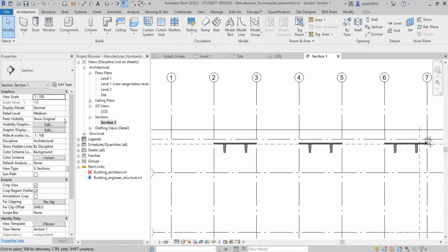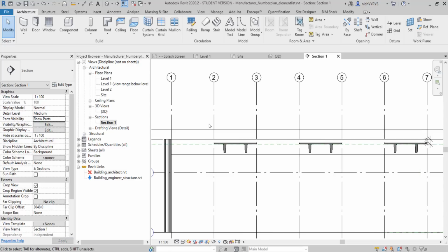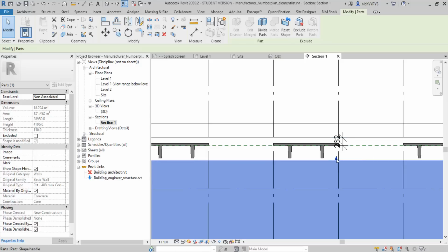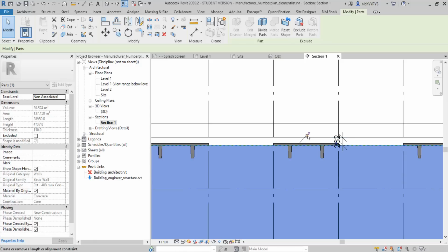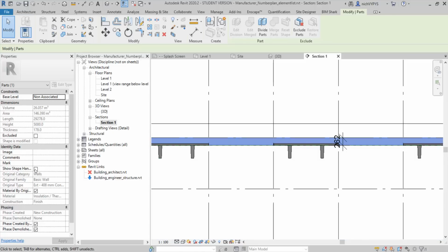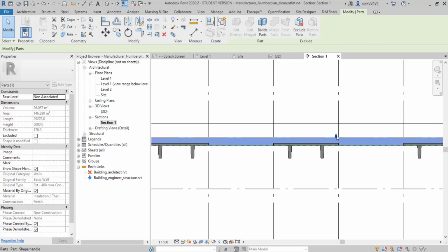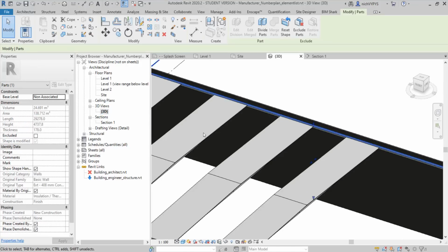So as I mentioned before, I would like to have the top of the inner leaf go to this reference plane that I made before, and I can lock them so that if I move the reference plane, then those adjustments that I make here will be followed by the reference plane.